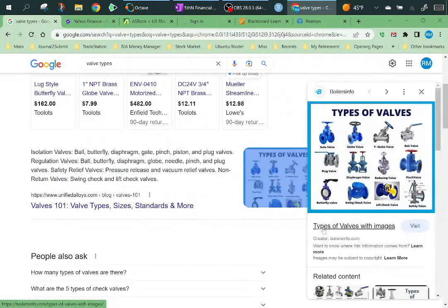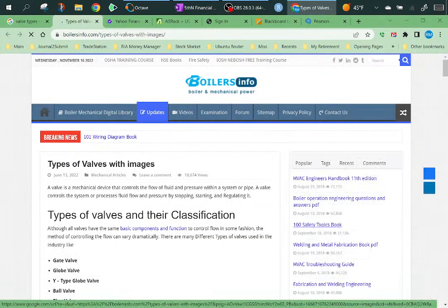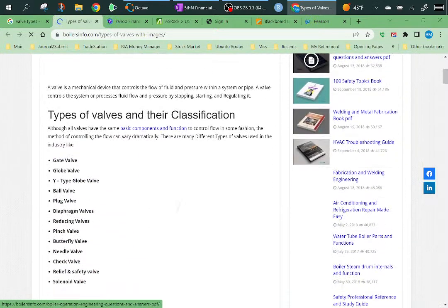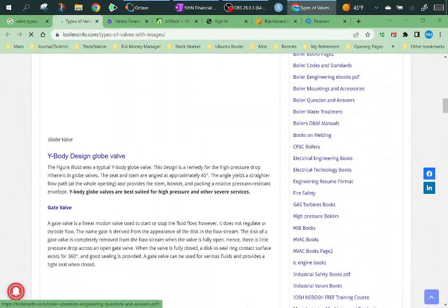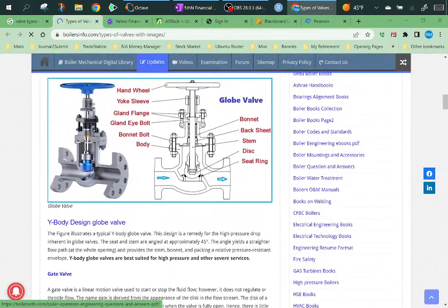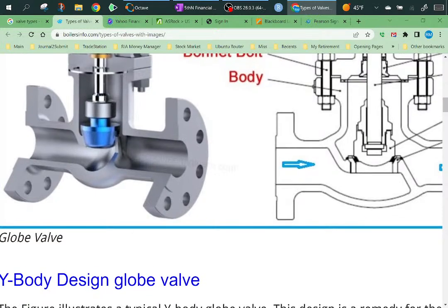Well, that's just an image, but often you can visit the place. Okay, so look at all these butterfly valves. I'm looking for actual, oh, here we go. That's the one I'm talking about. It's funny looking. It's kind of weird. You come off the seat, but that's really weird because the flow comes through there and it's swirling around to come down this thing. There's still going to be a lot of losses, even if that's completely open.